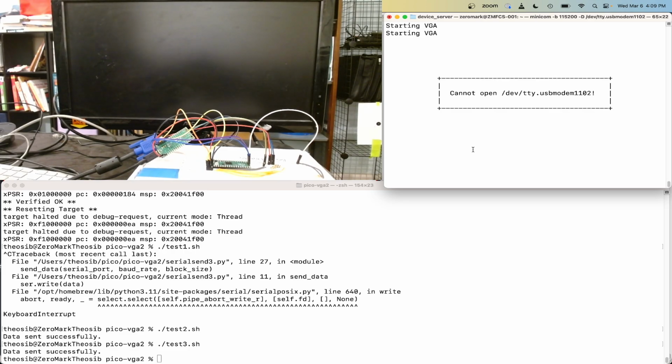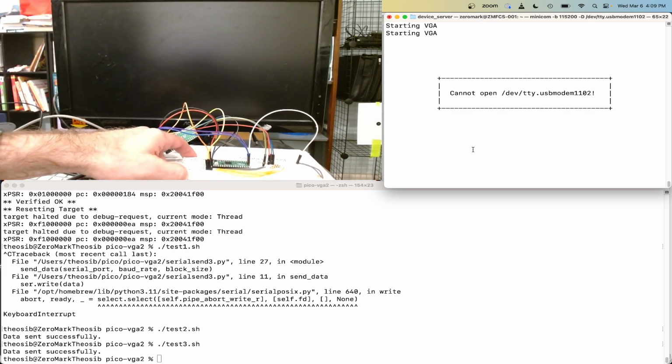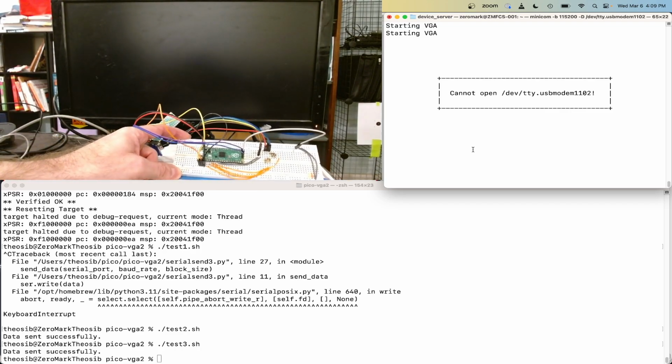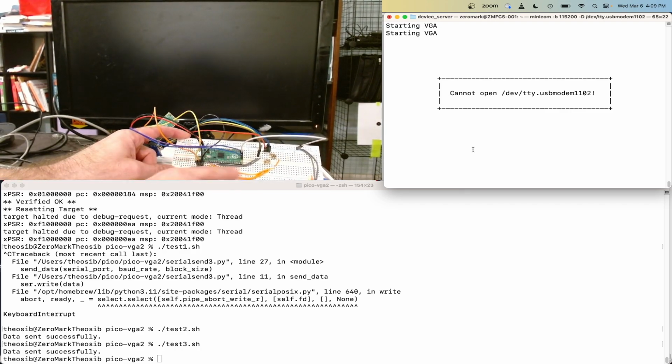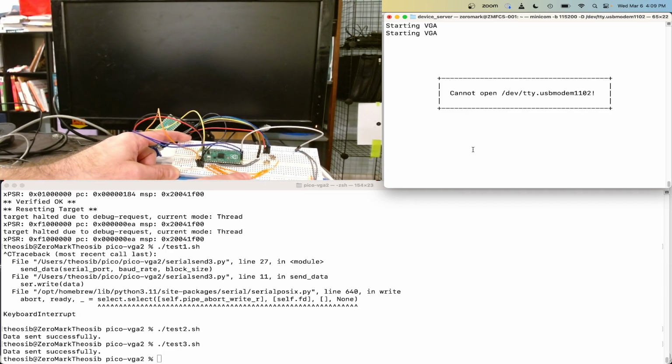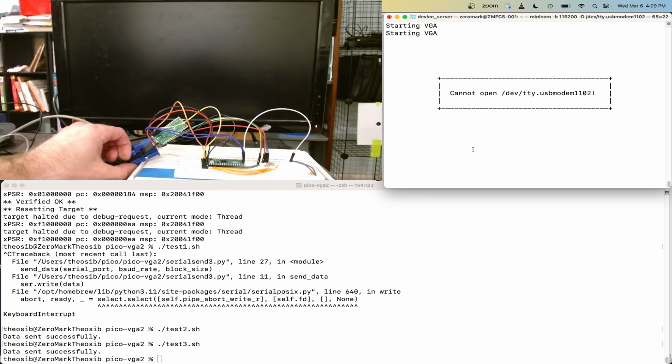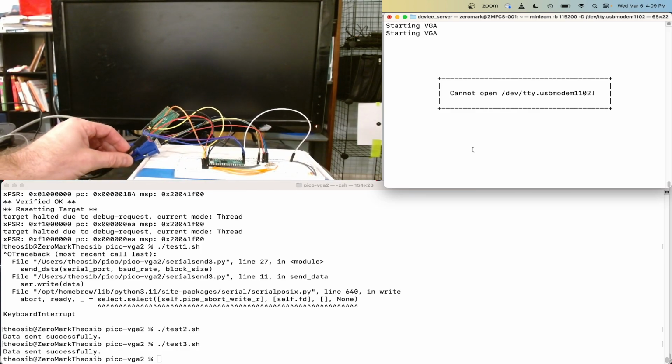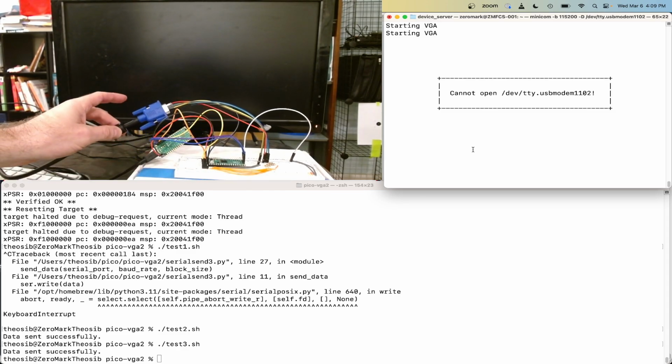And here we have the main Raspberry Pi Pico that is being used to drive the monitor. So here's the microprocessor. We have a resistor network for converting digital signals for RGB values into analog signals that can be understood by the monitor. We have sync signals that are also being sent to the monitor. And here we have another Raspberry Pi Pico configured as a Pico probe for debugging and reprogramming. And then here we have a VGA cable.